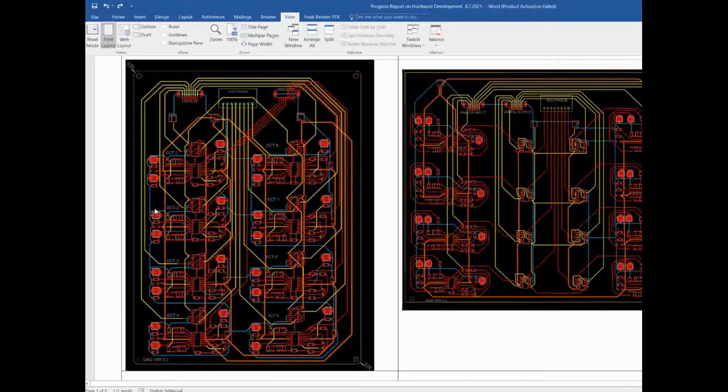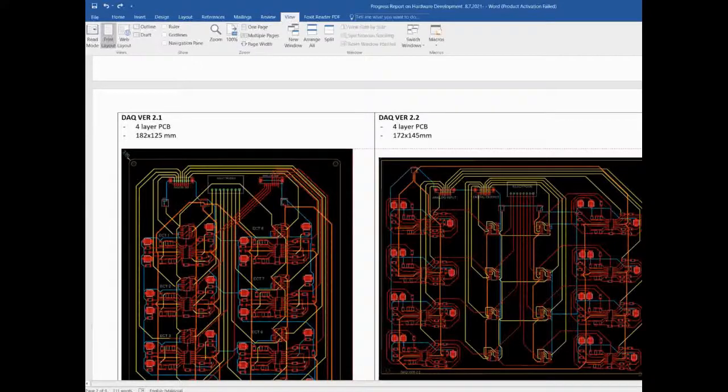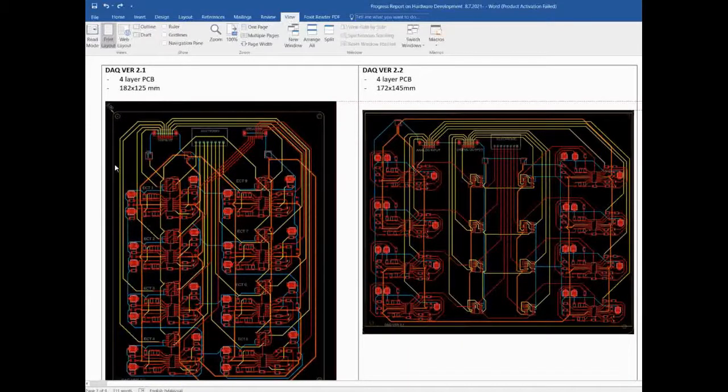So this will avoid my problem. Because this is not a simple one-circuit PCB, it is 8 circuits, 8 channels, there are chances that there are many signals on the PCB. So I thought I can't use 2 layers anymore, and I should consider designing a 4-layer PCB, and these layers can be dedicated to different traces.